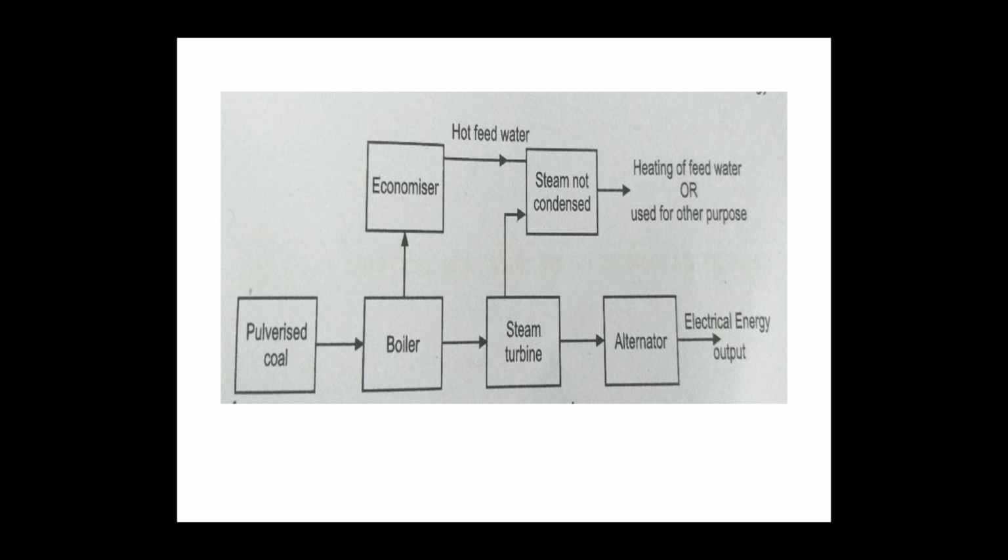The low pressure steam, that is the exhaust steam from the turbine, has a large amount of heat which is lost in condensing. If utilized either in preheating of feed water or for other factories, great energy saving can be achieved. At the same time, flue gases from the boiler going to the chimney can be used to heat other products of industry or houses, or passed through an economizer to heat the feed water to the boiler.